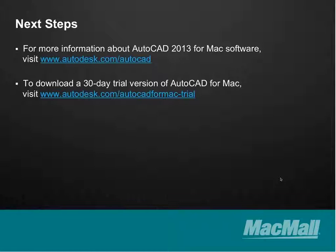So Mike Gilbert, you asked, is there support for VLAX within AutoLisp? It's a great question. The problem is, no, Visual Lisp is not supported in AutoCAD for the Mac because it utilizes Windows libraries. So it's compiled and everything using Windows-dependent files. And since the Mac platform doesn't have Windows core libraries, they aren't supported. That's the one thing in Lisp. So you can do almost anything in Lisp, but Visual Lisp. So the VLAX.